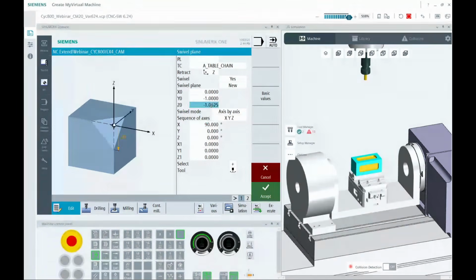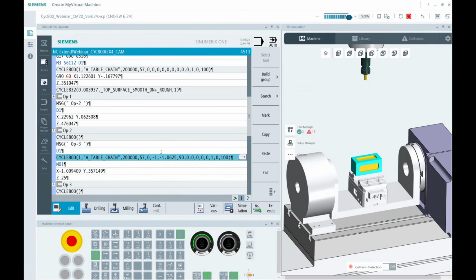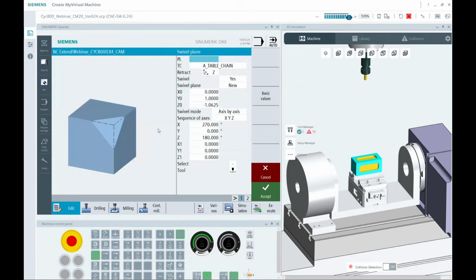You'll also see that they're plugging in some numbers and shifts. Now the CAM systems won't always do that. They may leave the 0 at where it was in the origin. I like to shift the 0 because this way, as an operator, I can tell at a look on depths and whatnot. So we'll explore that as we get a little further into it here. In this case, this is going to be a back surface. Now there's my 270 switch with a 180.